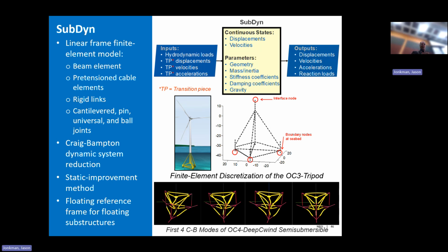And these are basically showing the elastic modes of that structure. If you have a finite element model like this semi or that tripod, it may have 1,000 degrees of freedom in it. You always get 6 Guyan modes. Those are what connect to ElastiDyn. But for the rest of the 994 modes, you can say this many are Craig-Bampton modes, and for those I'll do full dynamics, meaning I have a mass and a stiffness. Maybe you only want 10 dynamic modes. So now we're down to 984 modes left. The rest of those I could treat as static modes.